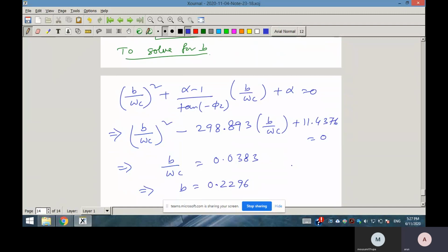If you do not assume that, then the phi 2, that is the unexpected phase lag provided by the lag controller, will be more, and the lead part has to provide much more phase lead to nullify it, which is not desired, which is not acceptable.